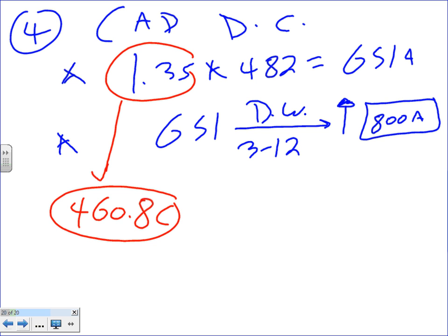Just a reminder, guys, Article 460 talks about capacitors. For you as designers, that's the most important thing in the article: how to size the conductor, the disconnect, and the overcurrent protection device for a capacitor. Where to put them, we'll talk about, guys, global and local, or main and local, how to put them, the advantages, disadvantages.